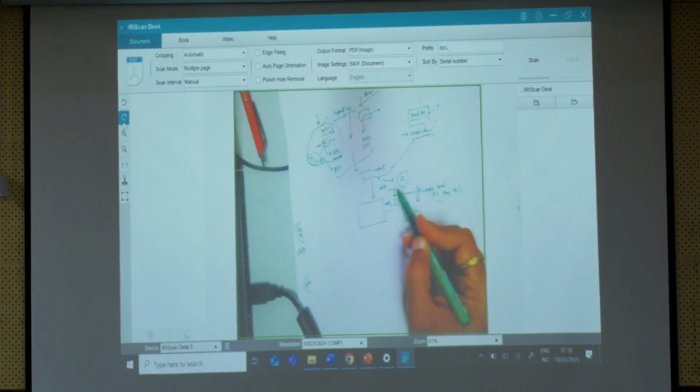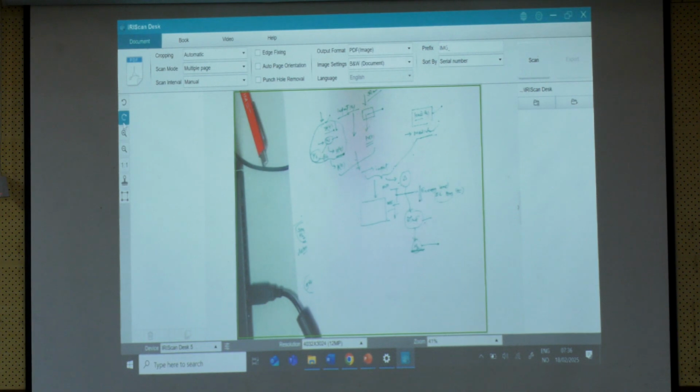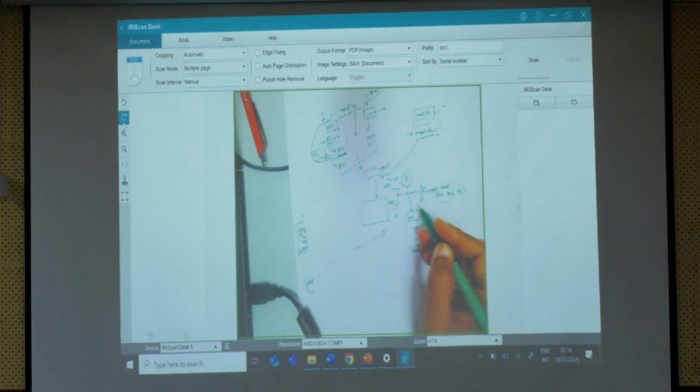If it is going below minimum level, not good, and above maximum level, then of course we have to pump more and more energy to the electrolyzer to put it back below the maximum level, and overall maximizing the hydrogen. And as a constraint to stop this system, we need to put as an input, if suppose there is any leakage, the system should be stopped.